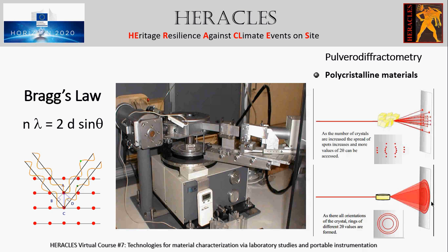The equipment to use is very simple in its design. It just has to observe the Bragg's equation for diffraction, where there is a relationship between the incoming and diffracted X-ray beams, depending on the distance between crystallographic planes in the structure of the material.